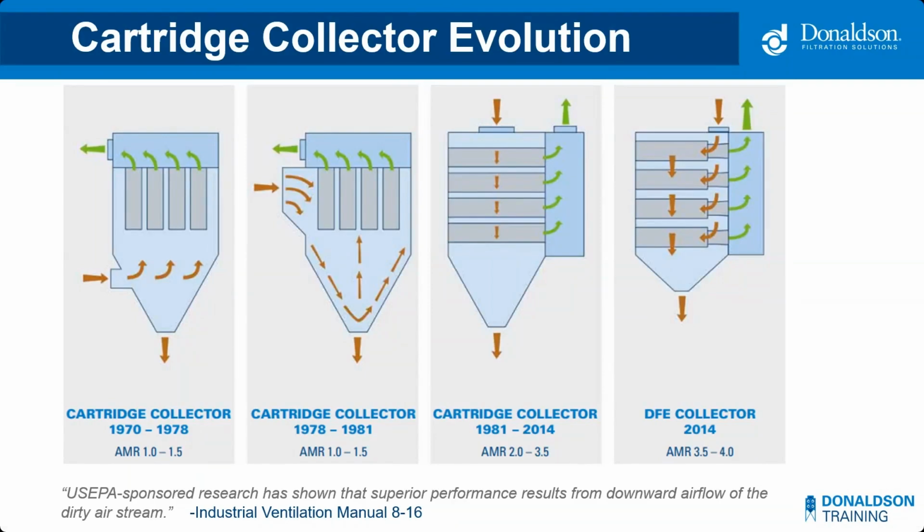So that upward air between the filters didn't really let those fine dusts work their way out of the system. As you pulse, that upward air was keeping that dust entrained on the filters. So next we move the inlet a little bit to allow gravity to assist us to bring the dust into the containers or the cabinets.